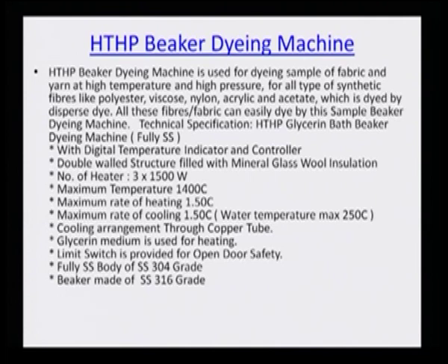Glycerin medium is used for heating. Why? Because water will only heat up to 100 degrees. So, if a higher temperature has to be attained, some additive has to be added so that it elevates the boiling point. A limit switch is provided for open door safety. The body is fully stainless steel, of 304 grade, whereas the beakers used in this machine are not glass beakers.